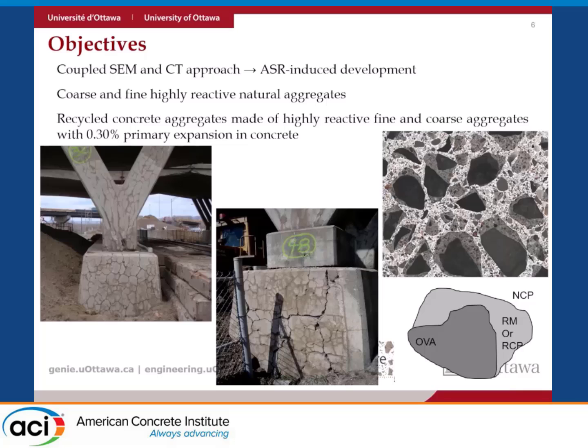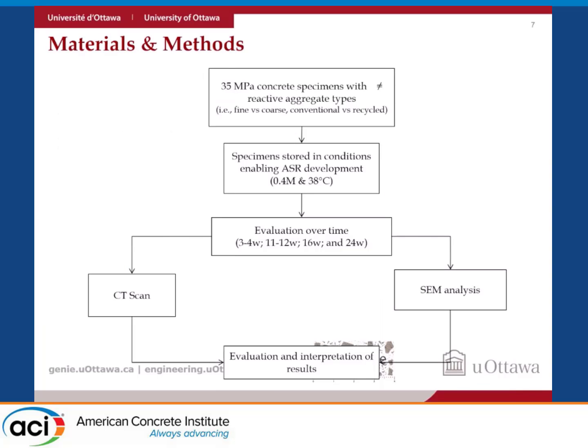But if what is causing the issue in the primary concrete is a sand embedded in the mortar, in the residual mortar, we don't know if that will implicate a secondary expansion or not. So what we tried to do was focus on further reactivity in the original virgin aggregate or in the mortar.